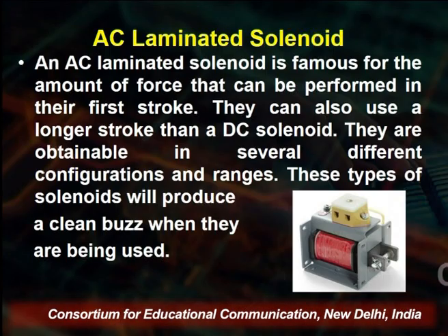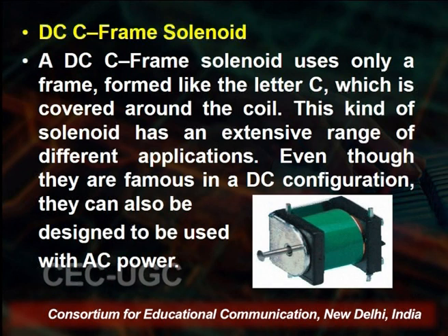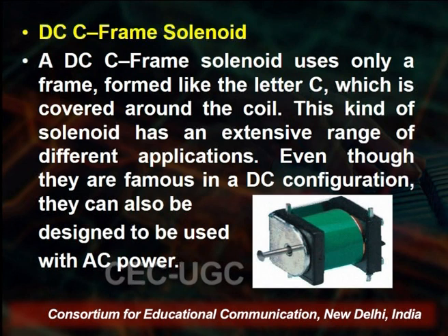On the right hand side, we have a different type of solenoid. This is the AC laminated solenoid, and it performs on the first stroke, meaning when we give it current, it works. Second is the DC C-frame solenoid, which uses only a frame, formed like the letter C.